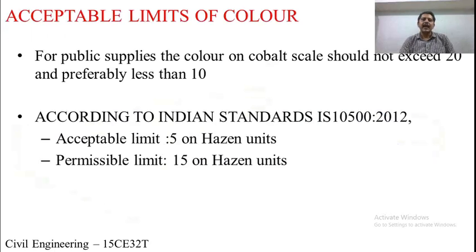So acceptable limits of color. What should be the maximum limit of color in the water? For public supplies, the color on the cobalt scale, that is the platinum cobalt scale, should not exceed 20 and preferably less than 10. Recent standards, that is Indian standards